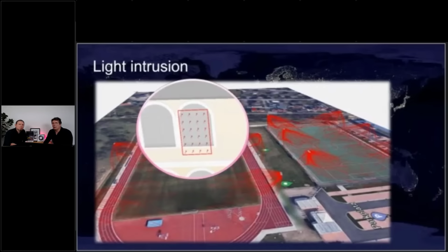A little bit you have to think about this when you make it in a project: we will not calculate maintenance values here. Typically we calculate maintenance values for a sports area or road lighting. Here we have initial values, that means at the beginning of the lifetime of a lighting installation.